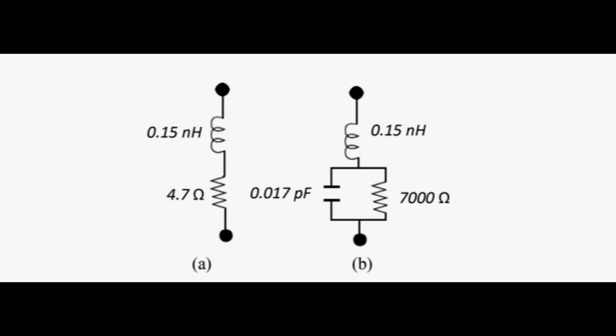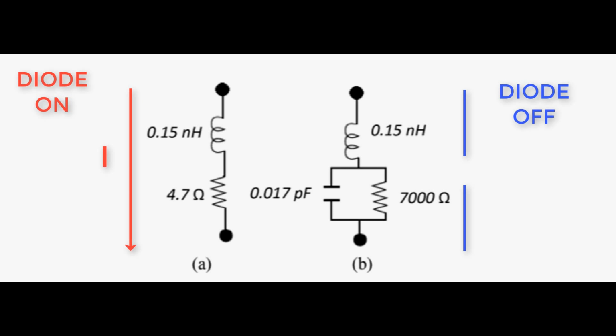Now we need the monopoles to be able to change from director to reflector. For that, we will use a PIN diode that works as a switch. When we feed the diode, the monopole attached to that diode will be short-circuited and therefore will act as a reflector.